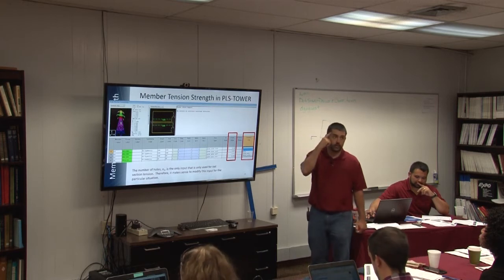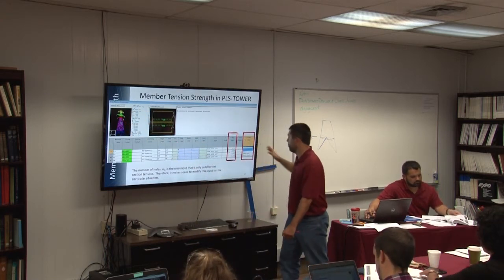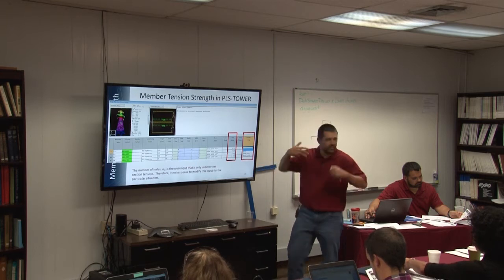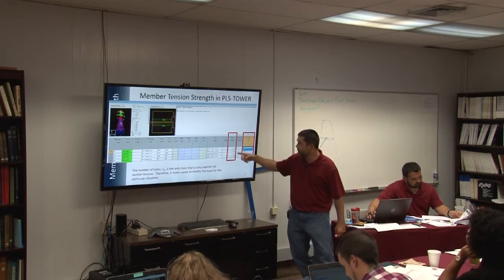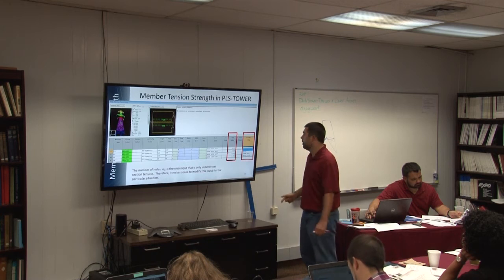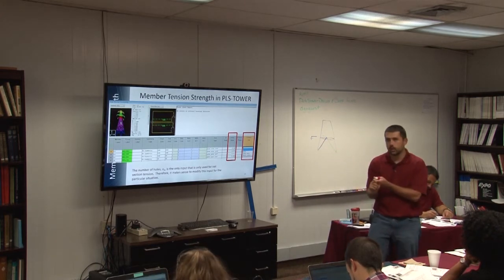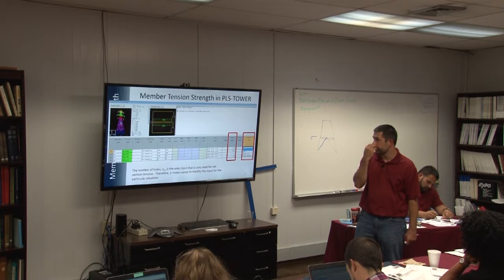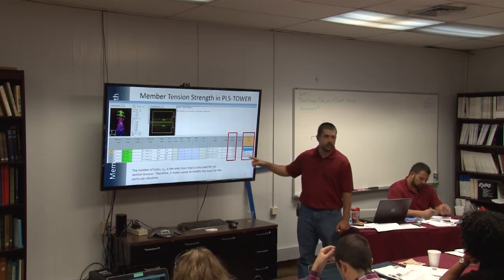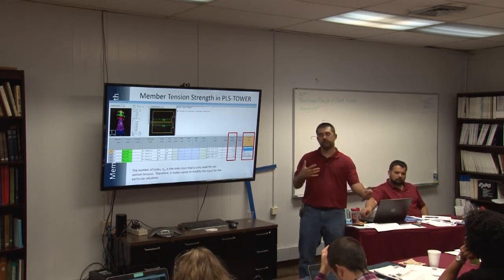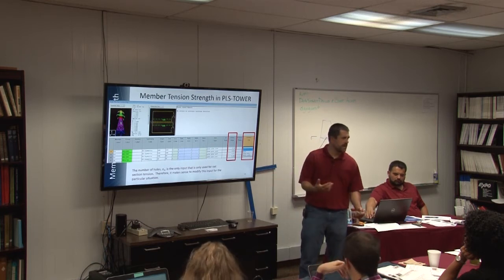So how do we control this? We're looking essentially at the member connectivity table. It's truncated. I'm only showing you the pieces that matter. For the net section calculation, what matters is the connected leg, for reasons we've discussed, and the number of holes to remove from the section. Now, for the issues that I talked about with staggered bolts or the clips and those kinds of things, how this works is that we have to input a non-integer value for the number of holes to get the program to calculate what we want. And I've got some examples to show you exactly how this works.